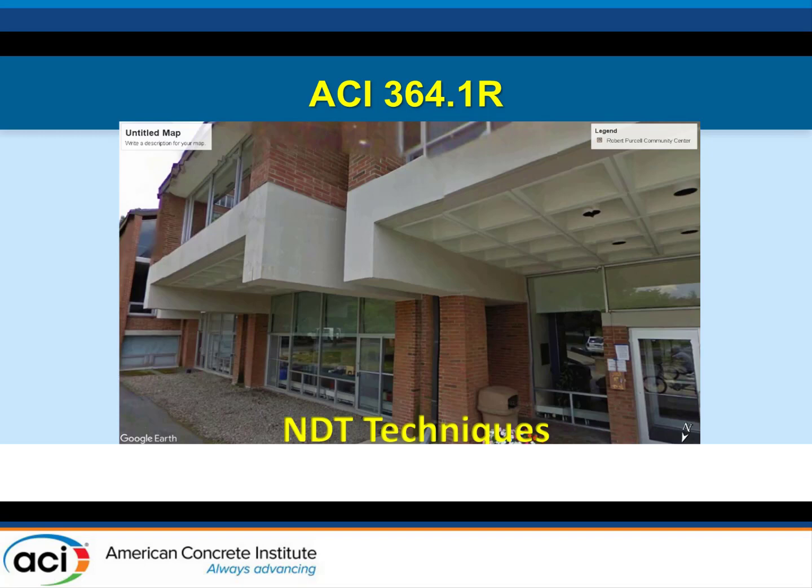So we came in very late in the stage, and our assessment really just did confirm the alkali aggregate reactivity. But at that point in time, it was determined that the structure really couldn't be salvaged. The owner wanted to keep the structure in service for at least another decade.